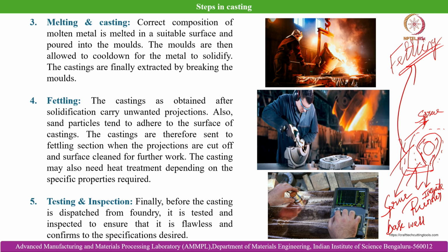And then testing and inspection. So once we have got the cast object, then before deploying it to in-service conditions, we need to inspect it. There are several destructive and non-destructive testing techniques available for that, like dye penetrant test, magnetic particle test, X-ray radiography.